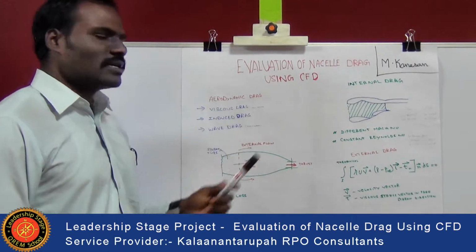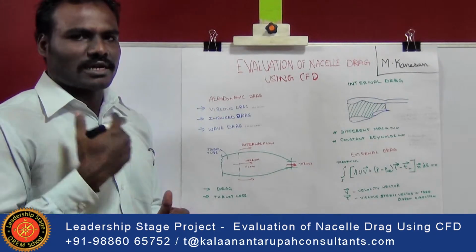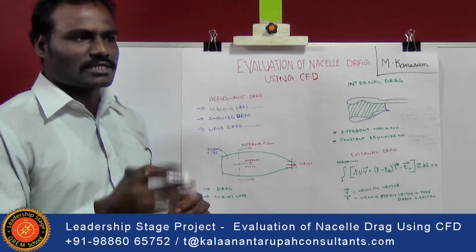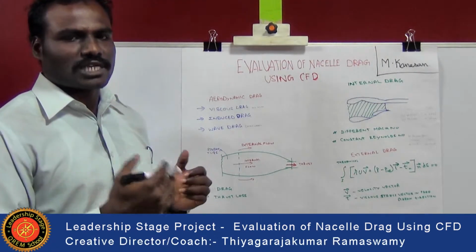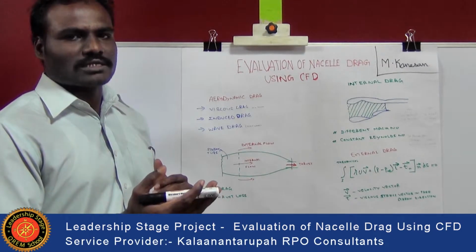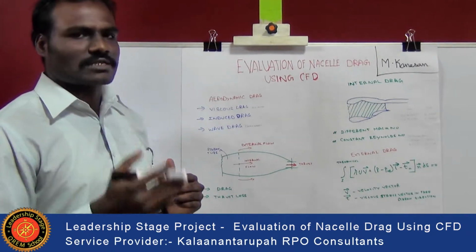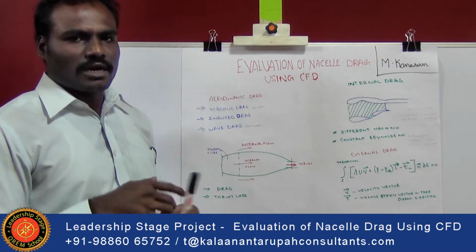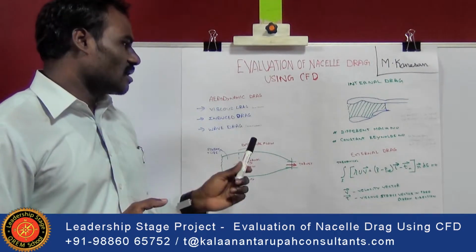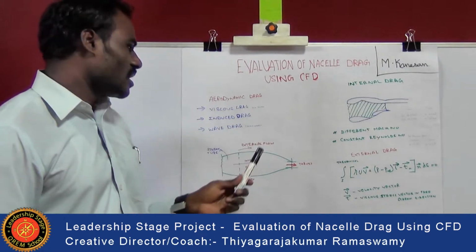The viscous drag consists of skin friction drag, which creates drag within the internal structure, that is, starting from the lip of the nozzle structure to its outer throat, the exhaust throat of the nacelle. The internal structure of this part faces skin friction, which leads to a drag.